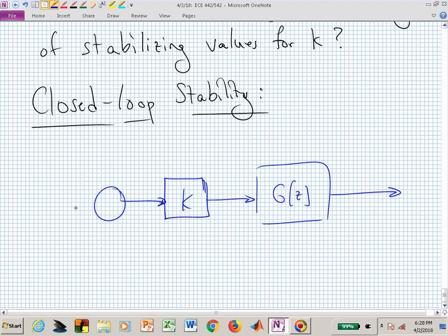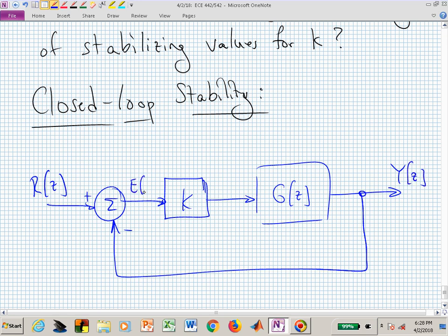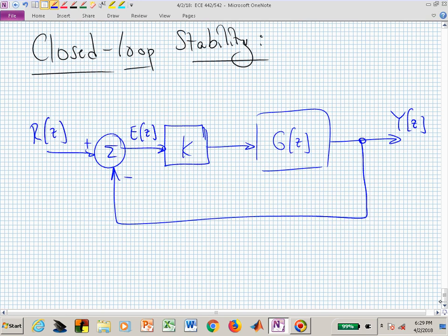And we now know how to measure the output, feed it back, compare it to the reference, and let that error signal drive the controller. The controller now is proportional. It just takes that error and scales it and then injects that into the input of our plant, of our system. That's the block diagram that you see for a closed loop interconnected system with a proportional controller.